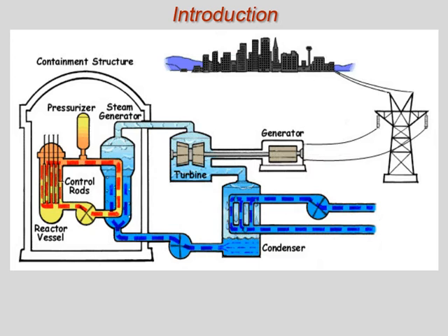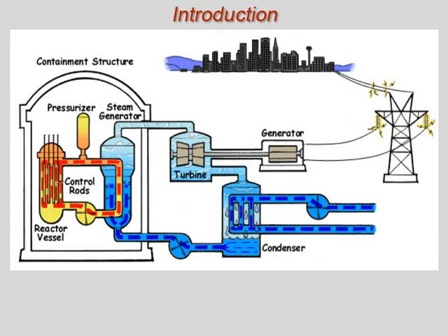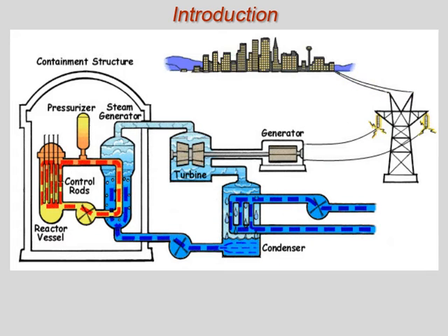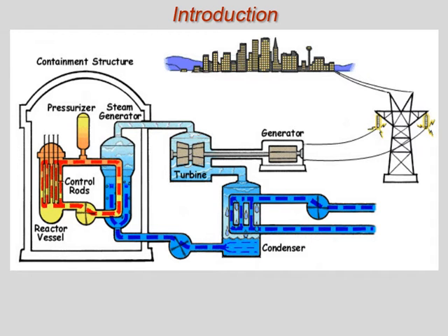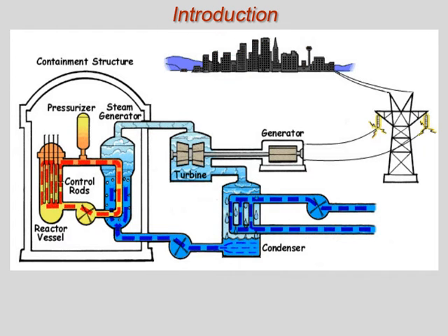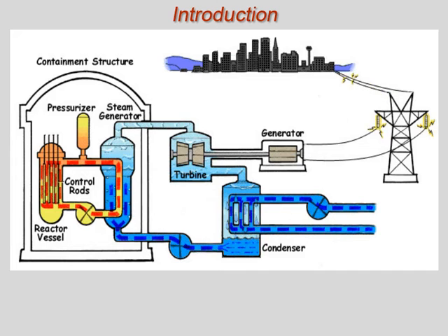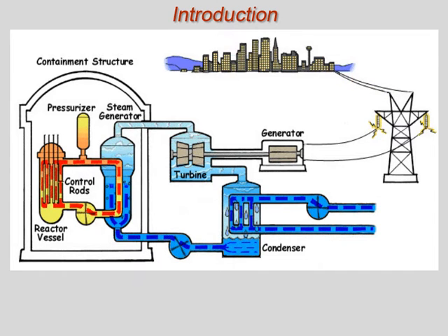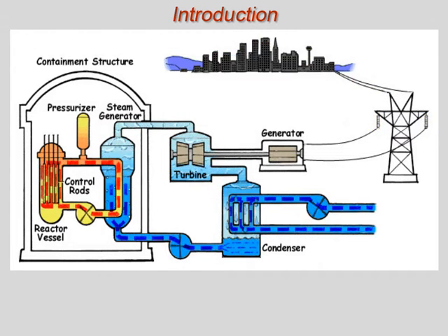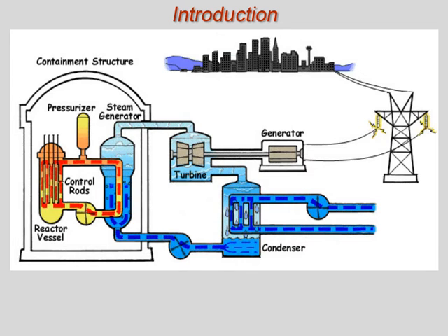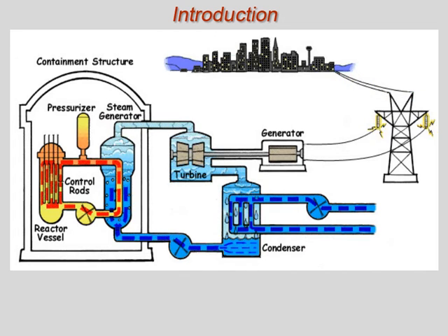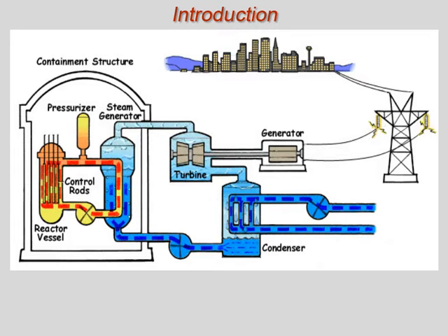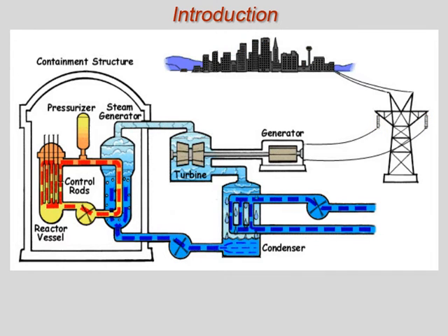Steam systems at SRS provide high-quality, low-moisture content steam at the required pressures and flow rates to systems and components, while also providing a positive means of preventing the spread of radioactive contamination. The steam systems supply heating steam to ventilation system heating and humidification units, component heaters, heating steam for the various process systems such as evaporators, and other miscellaneous loads.